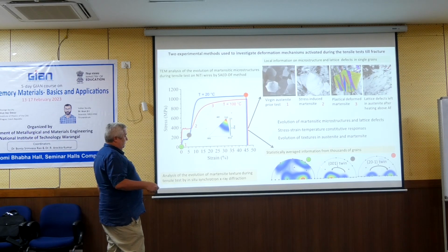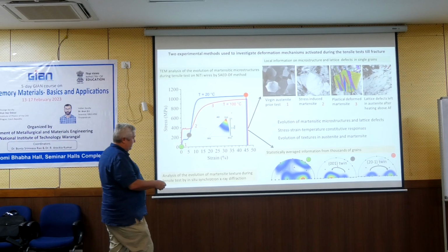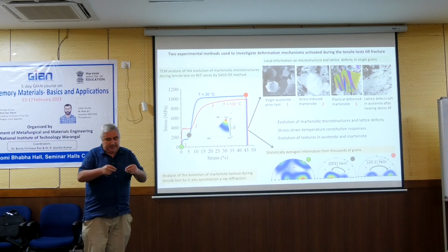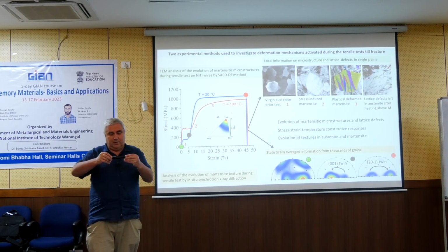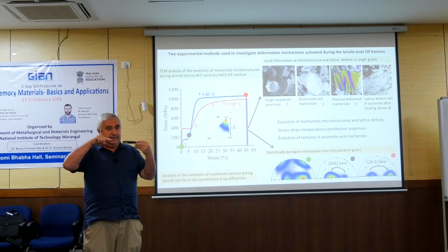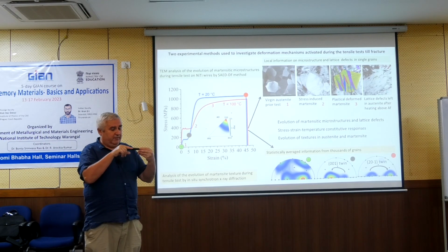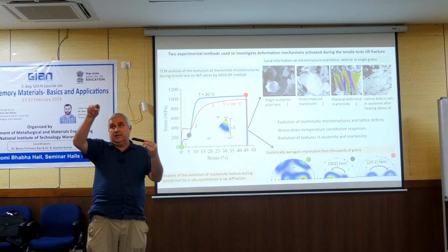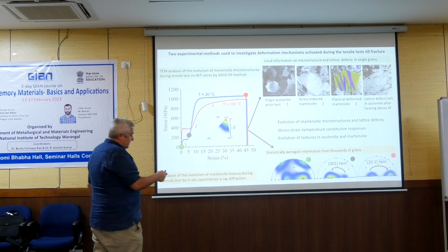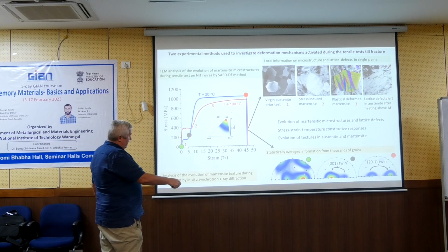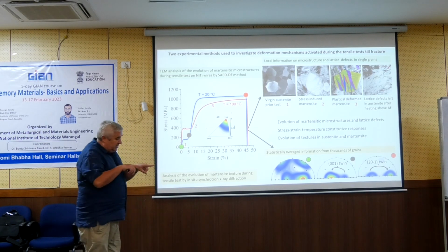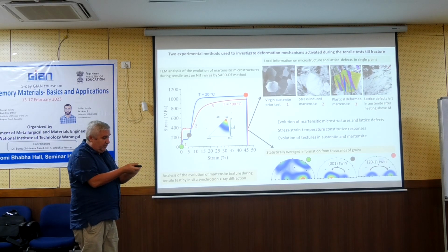I'm not sure if I have further slides, so I will explain it using here. The wire has a 111 austenite texture, which means that most of the grains are oriented with 111 diagonal direction along this line. And now this is plotted by this triangle. This is in austenite, and now I am in martensite. So martensite is a monoclinic lattice, so one triangle is not enough. I have to plot all this, but I am still interested in what is the crystal lattice direction along the line.